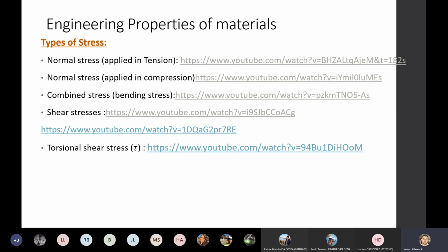Just to answer you, Fabio, with concrete itself, it has never been an issue to increase the compressive strength. There are lots of options to do that. Mainly it's creating the balance between concrete and steel, and sometimes confining the concrete is the bigger challenge. Confining it means keeping it within that shape.